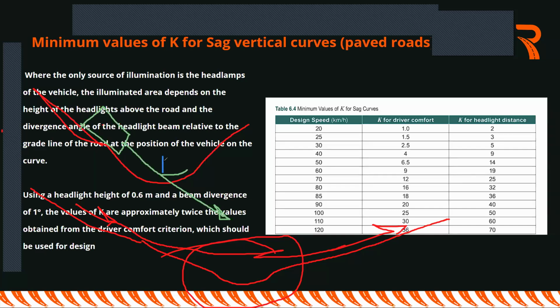It will serve us. So if a vehicle is driving downhill at this point, you'll notice that they will be having headlight glare at this area. And the same scenario happens. But then if the road is a little bit, the curves are a little bit gentle as possible, you will notice that the angle here will be uneven. And therefore you won't be having much of headlight glare at the crest curve.